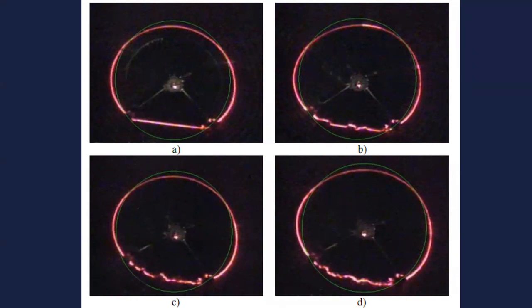So instead of having to pull a mandrel and do CCTV, you can actually do both. You darken the line, you run the laser through, and then you lighten it, and then you run the camera back through, and you can do it all in one take. So you can just go down and back, and down with the camera, back with the laser, or however you want to do it. So that's a great option that we can do.